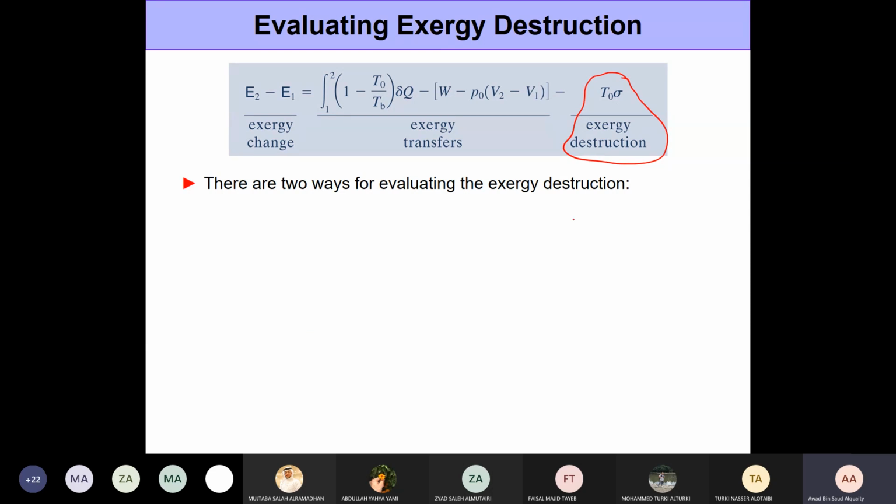Always the idea would be, once you have a list of different components, let's say compressor, turbine, heat exchangers, and the order of Exergy destruction, then you can make a choice where you want to start by reducing Exergy destruction and improve the overall efficiency and also the exergetic efficiency of the plant or the engine, right? Ways to increase the output.